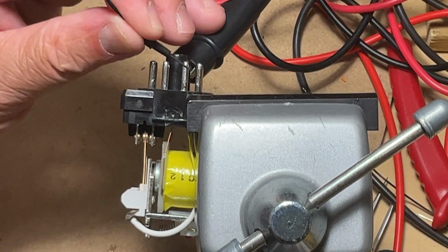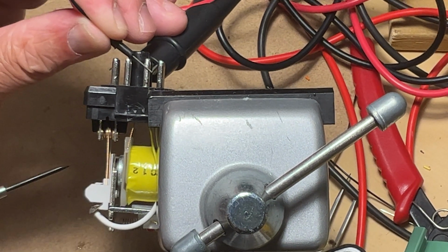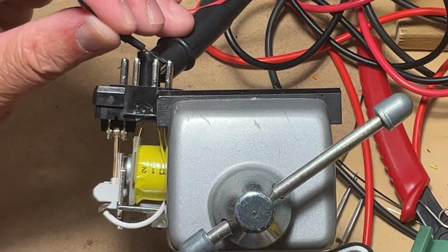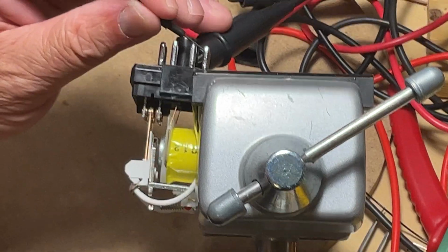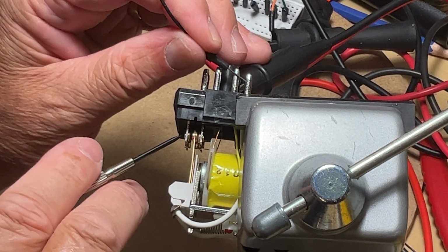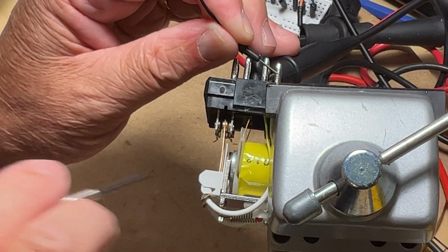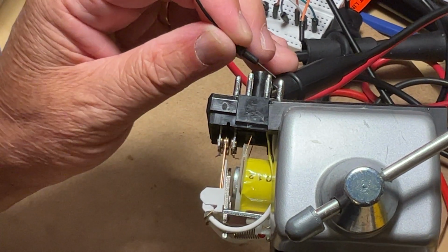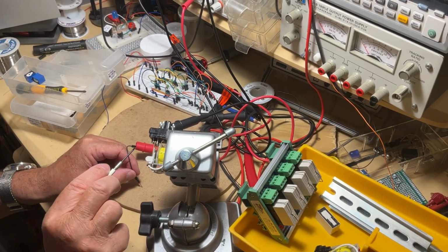As soon as I touch and close the contact to energize the coil, that plate right here, you can see now, is the only moving part. It's toggling between the two other contacts. So here on my left is the normally closed. When I energize, the coil is opening. On the other side is the normally open. When I energize, the pole is touching it. See? This is how it's working. So remember, coil and contacts.